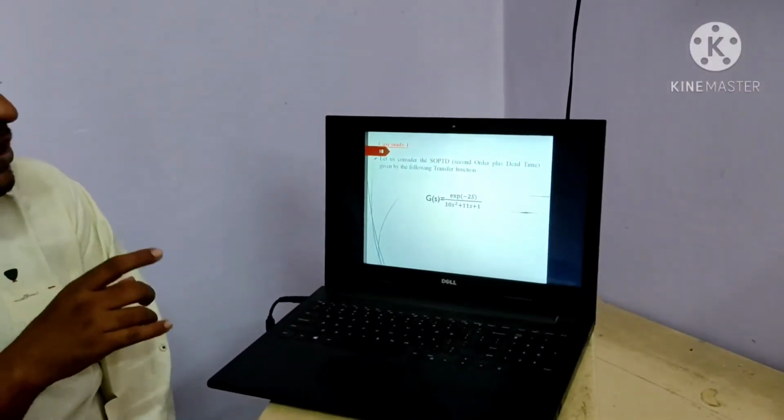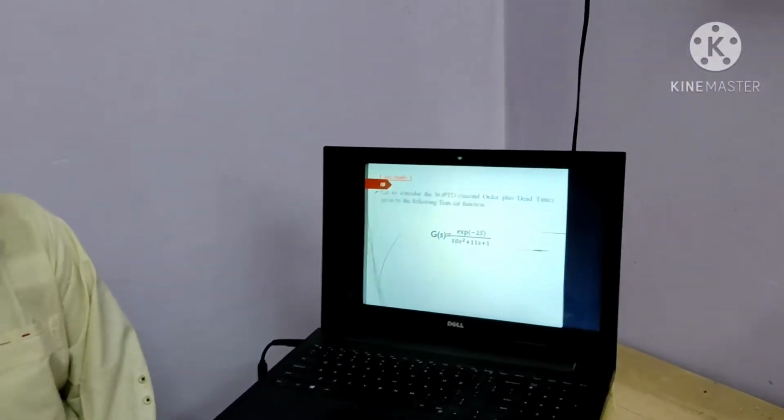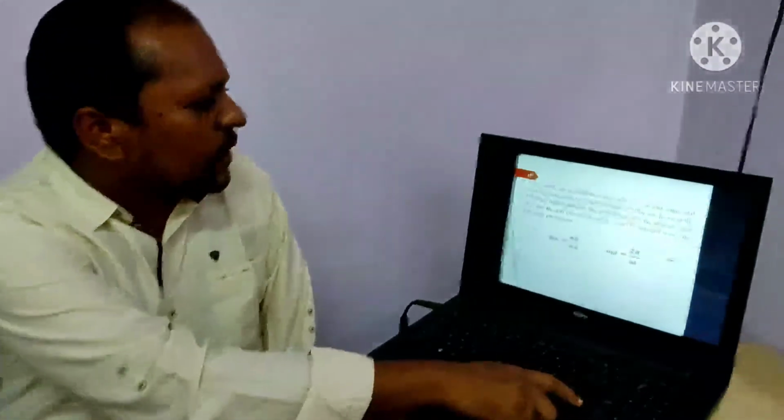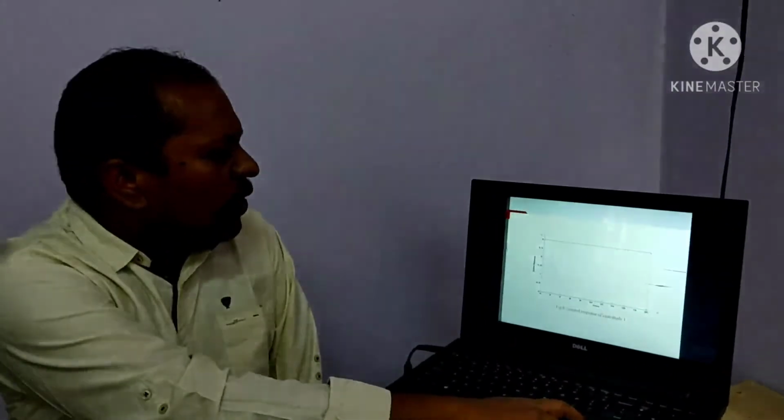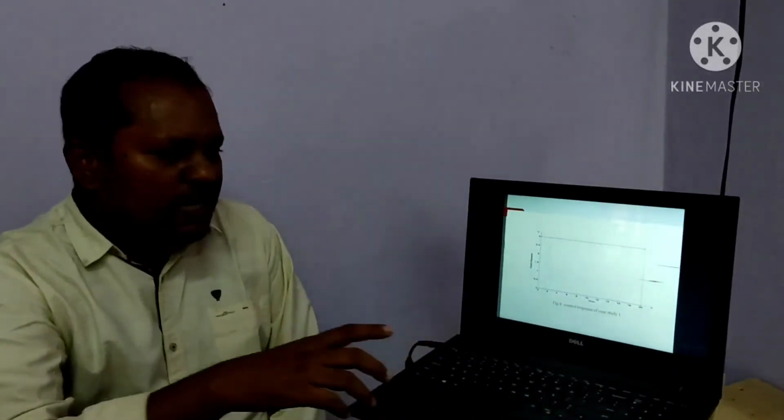That is the order of the system. Now let us see when the system is second order. Order is 2. A second order system is nothing but the inverted pendulum. The inverted pendulum is one of the best examples for the second order system. So now let us identify these process parameters Ku and omega u, and these are the sustained oscillations we got from this, and this is the control response we got. Control response means it will show how the process runs over time.